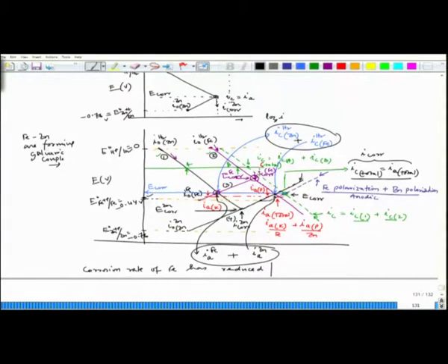But after coupling, I could see that the corrosion rate of zinc has gone to this value at this point, the IA is much higher than the IA what used to be here before coupling. So, the corrosion rate of zinc has increased.